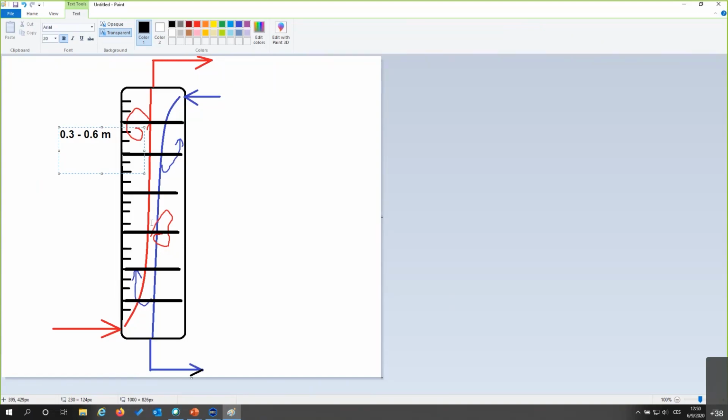If you are at a very early stage of process design and you haven't decided on the geometry yet, you might want to use the ideal stage model just for the initial mass and heat balance. But when it comes to a little more detailed design, to really get trustworthy results and to not worry about HETP, our recommendation definitely is the mass and heat transfer model.